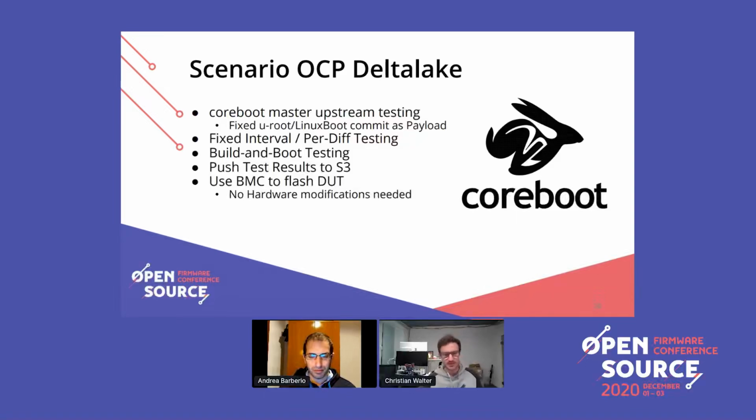The nice thing here is that we can actually use the BMC to flash the device under test, right? So that means that there's no hardware modification needed for that, so there's no soldering whatsoever involved here.